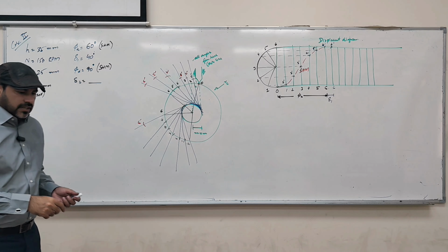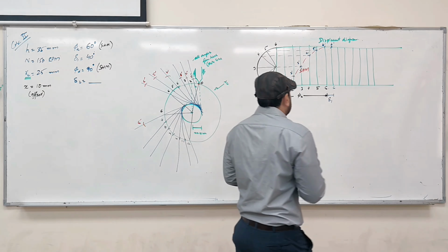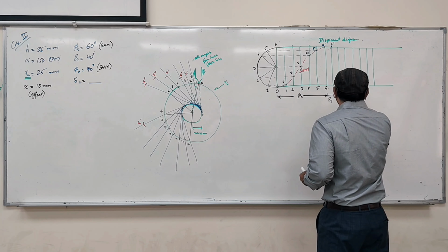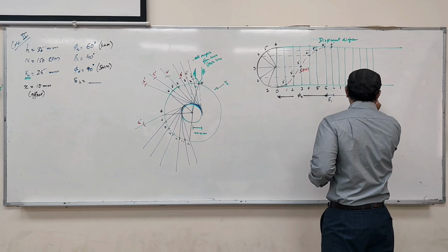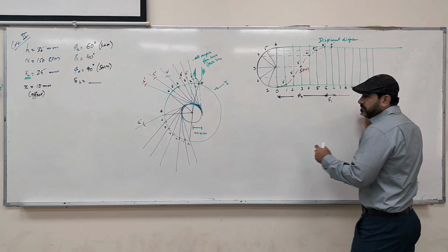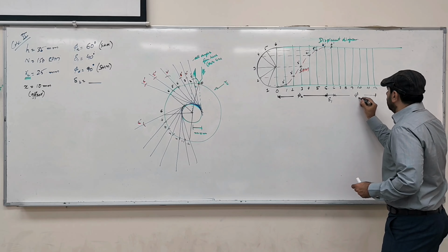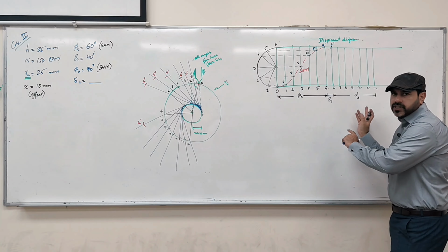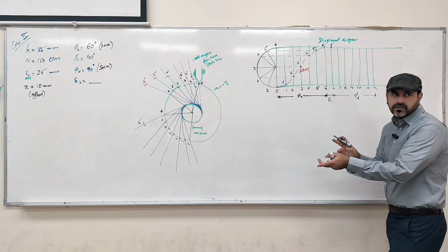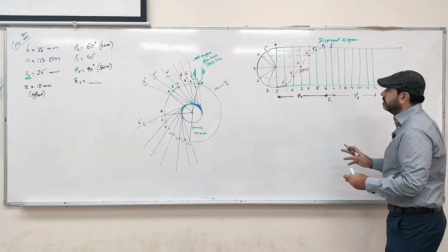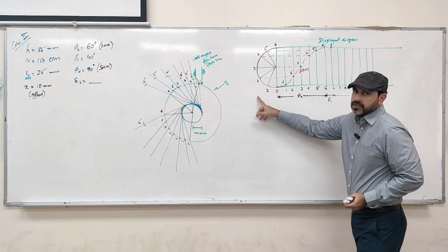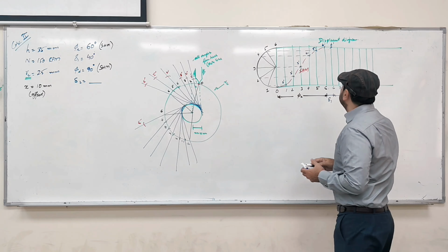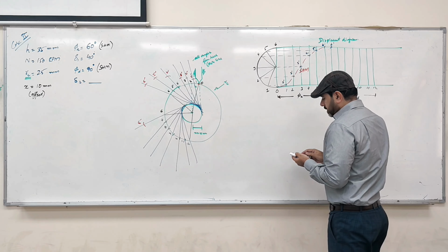Okay? Now go to the other side and see we have 6, 7, 8, 9, 10, 11, and 12 from here to here. This is very important labeling as well. Otherwise, we don't know where the points are going from here to there, so a person who is going to review it cannot do it. All right, because we have 6 divisions, because it's a simple harmonic motion, we'll take the same references. So this 5 will become over here with this line.